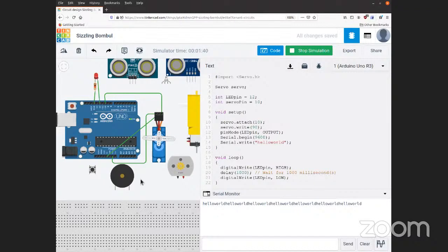Making it beep and blink is another way to debug. Blink every time you get here. That is actually a useful way to debug, along with an oscilloscope.